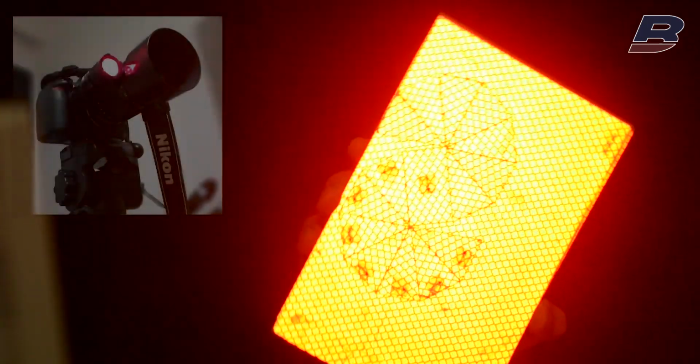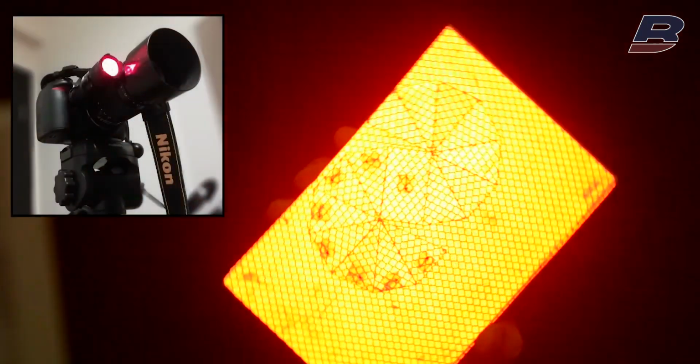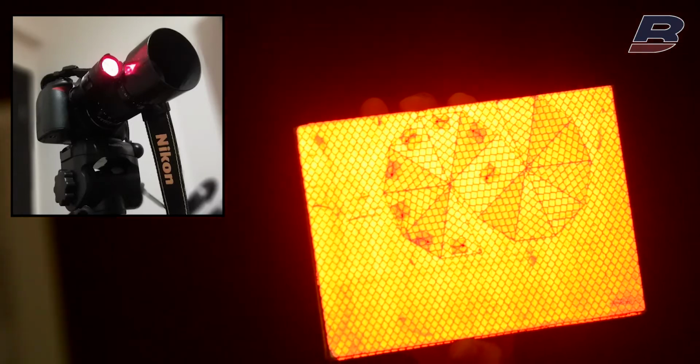Hello everybody! Today you will learn how orientation of retroreflective sheeting affects nighttime appearance of traffic signs and how to avoid being tricked by unscrupulous manufacturers. Unlike glass beads, microprismatic retroreflective sheeting is sensitive to its orientation. It can be easily observed even under ambient light, and of course you will see a difference in retroreflection of prismatic pieces with different orientation.